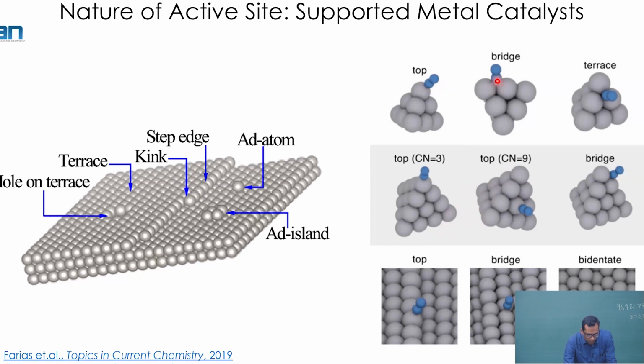So at time 0, we can see the darker points here, which are the nickel particles. They are spread over the surface of this magnesium aluminate, and over time, after 10 minutes, we can see some of these nickel particles now have grown to a bigger size, and the smaller ones have disappeared from the surface. And given more time under the reaction conditions, now those small particles are almost vanishing. So this is an example of how, through characterization under reaction conditions, or close to a reaction condition, we can see the transformation of the catalyst surface and understand how the catalyst deactivation is happening.